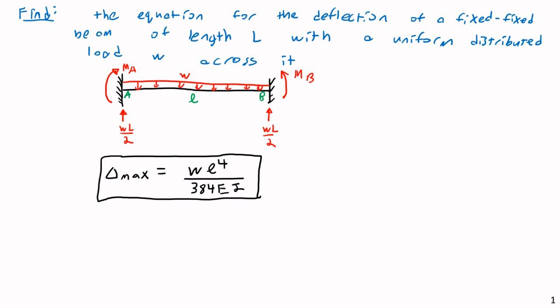I could solve for the equation of deflection on a fixed-pin, a fixed-roller, a pin, a bunch of others. I could have a fixed support here, and a roller in the middle if I wanted to. The force method really is truly a very versatile and very powerful tool.